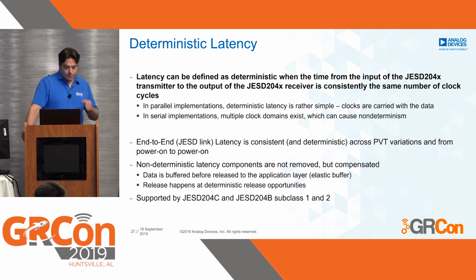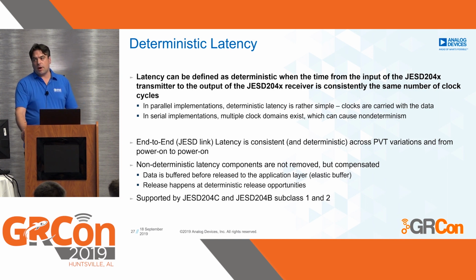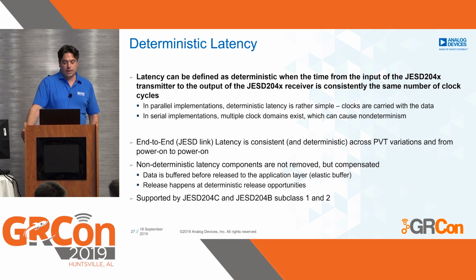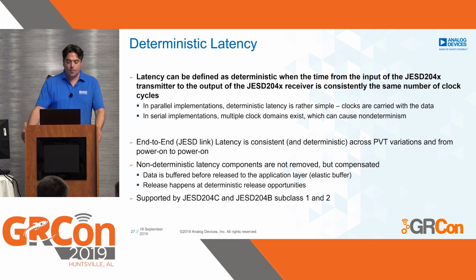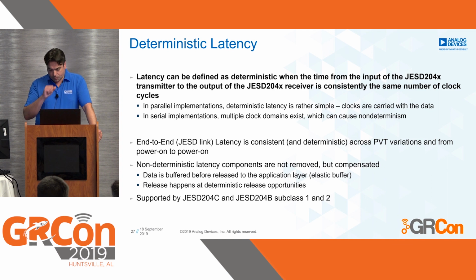The standard says that end-to-end latency is consistent and deterministic across PVT and also between power cycles, link up, link down, and so forth. All the non-deterministic components are not removed, but they are compensated, and that is something I want to talk about a little in the next slides.